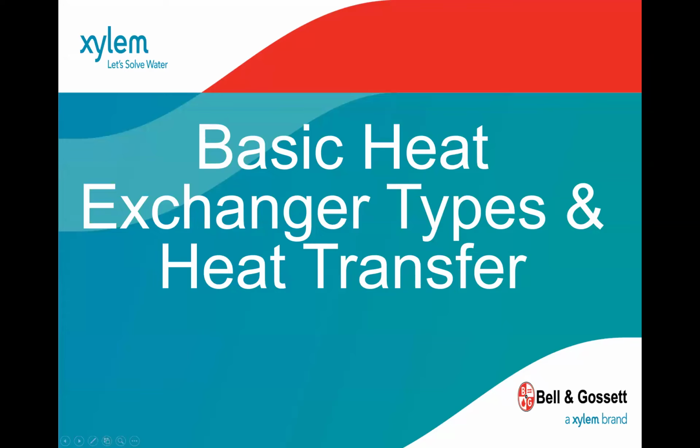Allowable pressure drop. So you need to have these items to be able to determine what conditions, and then you need to have, say, your pressure drop. I think the default on our platform is 10 PSI, but I often change it to about 15 feet of head. Mechanical requirements, so any design constraints, materials, space. The height of the heat exchanger or the frame sometimes can be very large. So you'll notice in the platforms, we'll give the dimensions so that can be a factor, and then you can see the relative price as well.